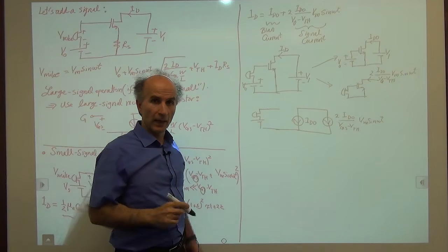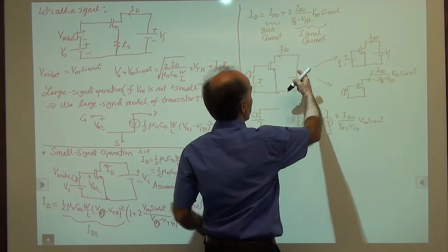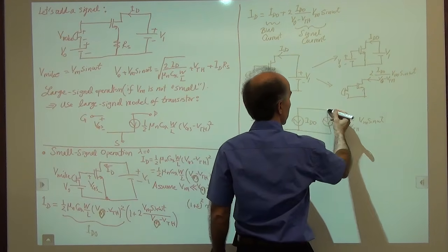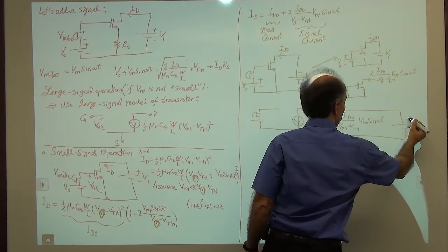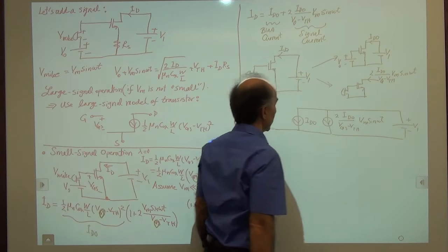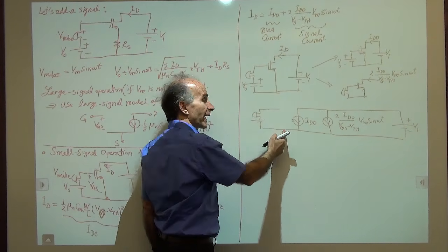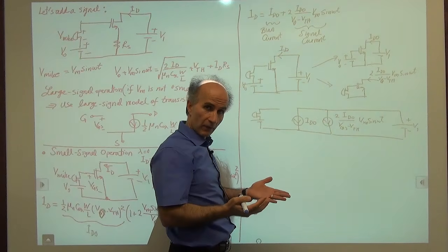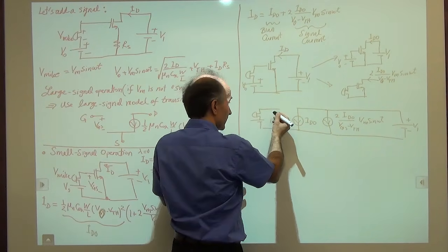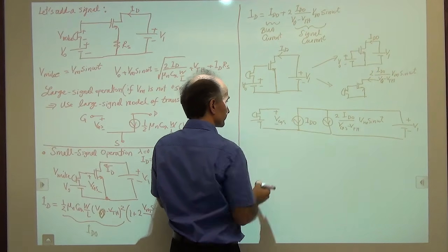All right. Now, it's a little strange, but I guess I would need to draw this battery as well just to have a complete situation. And that's okay. We'll draw that too, V1. And that's the overall picture, right? Between the gate and the source, we don't have any impedance because the current drawn by the gate is very small. But we still have a voltage here, right? That's the VGS that we have. That's the total VGS that we have.